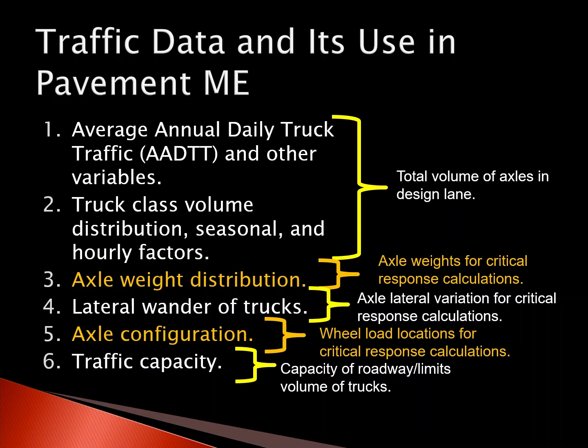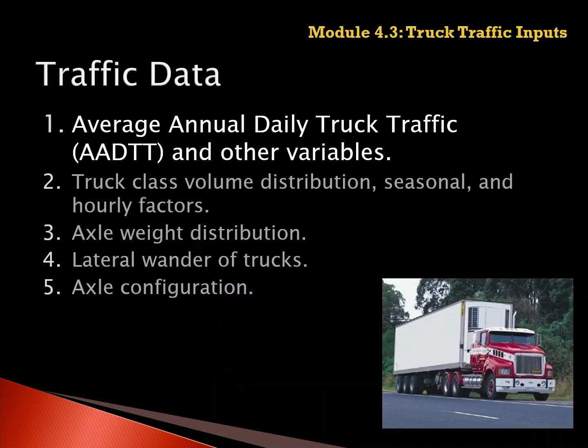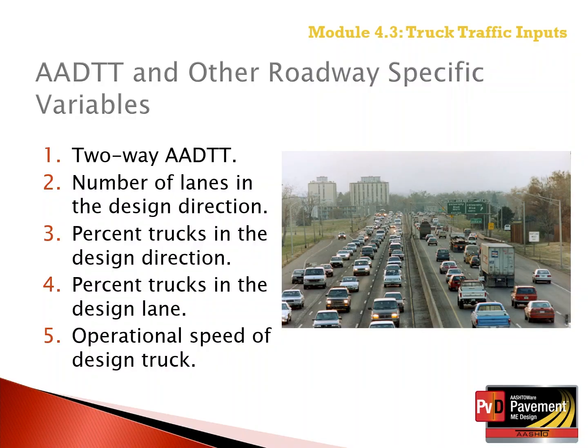And then the sixth, traffic capacity. It's the capacity of the roadway that limits the volume of trucks. And again, it doesn't have an impact on the predicted pavement distresses unless the capacity of the roadway is exceeded. Now let's focus on the average annual daily truck traffic and other variables in the Pavement ME Design software.